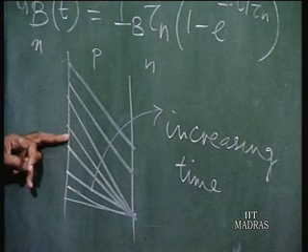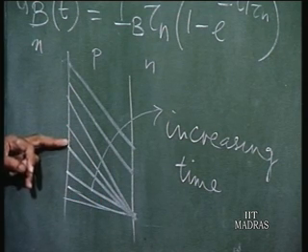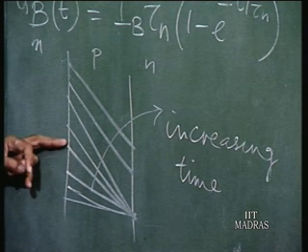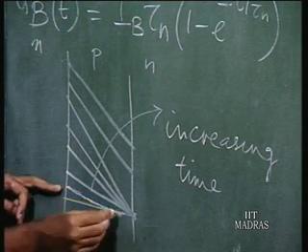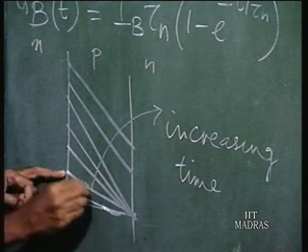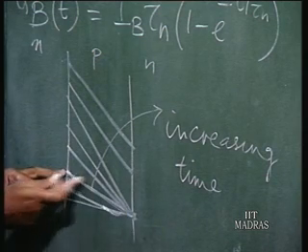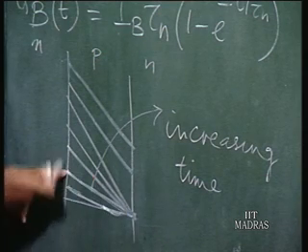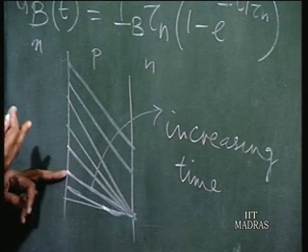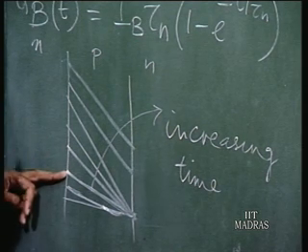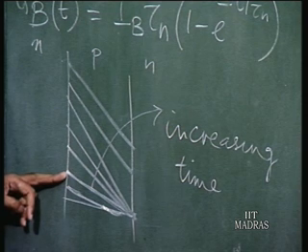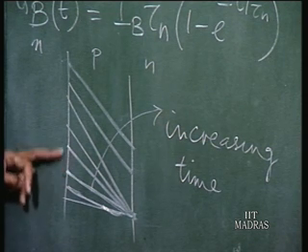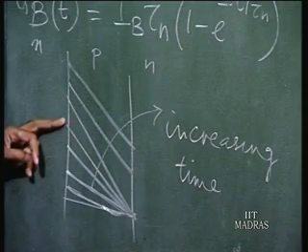What is happening to the collector current as the base current is with time? Collector current is increasing. For example, here you see it was initially 0, then it went to here. So, the collector current depends on the slope of this profile. Okay. So, that keeps on increasing, and as the collector current keeps on increasing, what happens to VCE? It goes on decreasing. Okay. All right, is not it? And so, the collector current goes on increasing, VCE goes on decreasing.